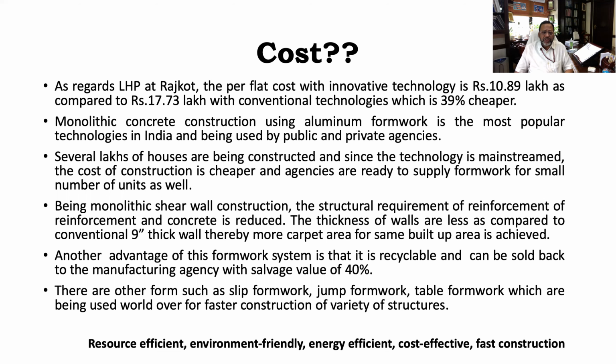this construction technology. Also, in addition to tunnel formwork and aluminum formwork, there are several variants which are very popular the world over, and especially used for high-rise structures, for casting mass concrete, for doing large slabs, large span bridges, and all these things. Those forms are slip formwork, which can be used for very high-rise structures, and jump formwork and table formwork, which can be used for construction of large slabs, and it enables very fast construction.